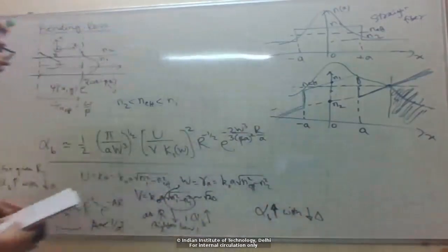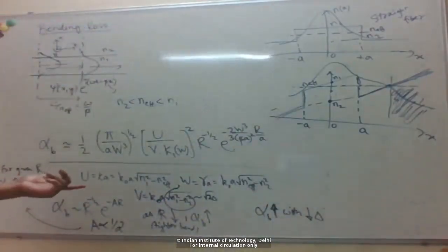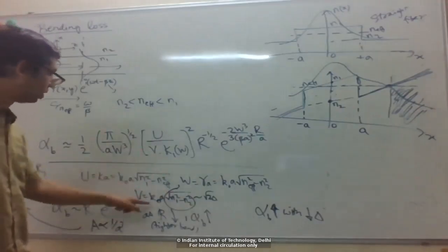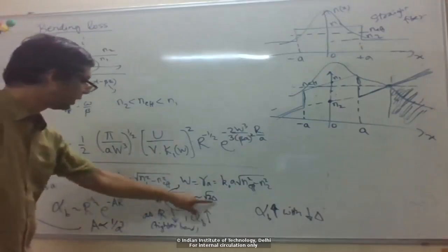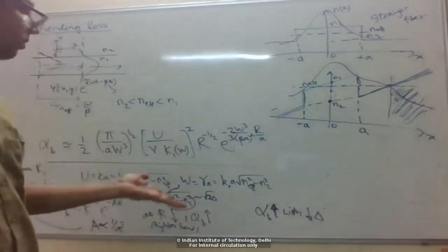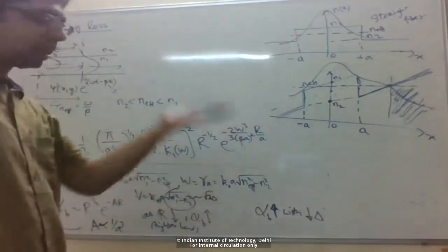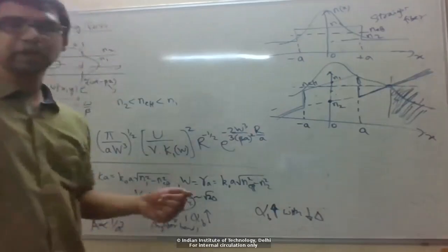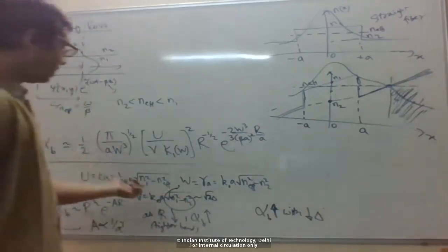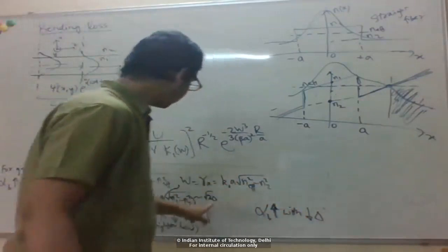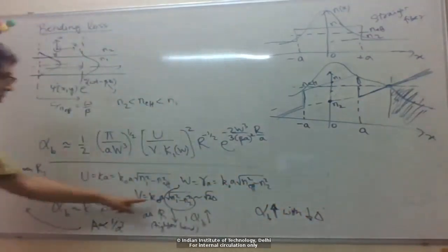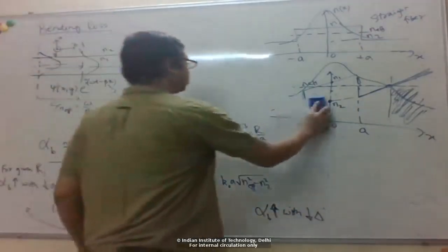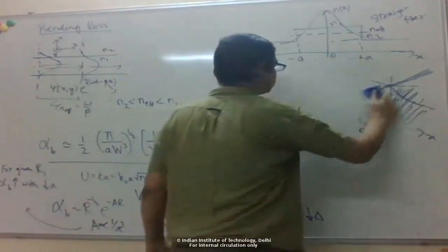So you can see that these are actually significant for single mode fibers, right? For single mode fibers, for example step index, we want V less than 2.4, which means that the core size and the index difference have to be small. We can't just make them larger and larger, because this V number has to be smaller than a particular number. But we see here the bending loss goes up with smaller delta and also smaller core radius. So for single mode fibers, you have to be careful of this bending loss.